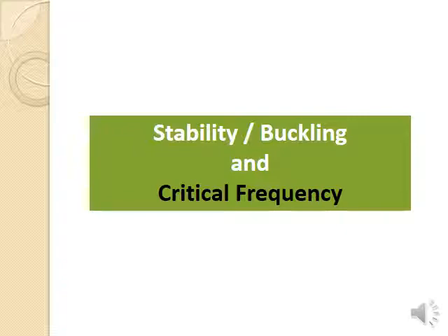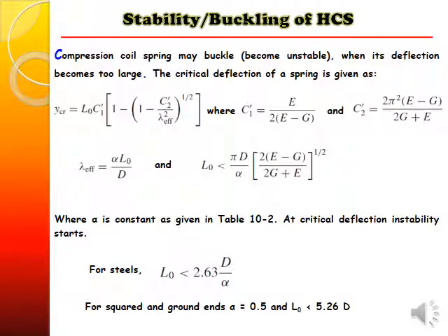Now we will look at a few of the issues before we see how to design springs against static and dynamic loads. One is the stability or buckling and critical frequency. The helical compression spring can buckle, meaning it will become unstable when the deflection becomes too large.